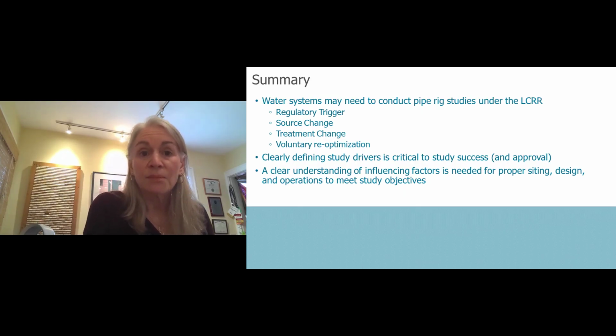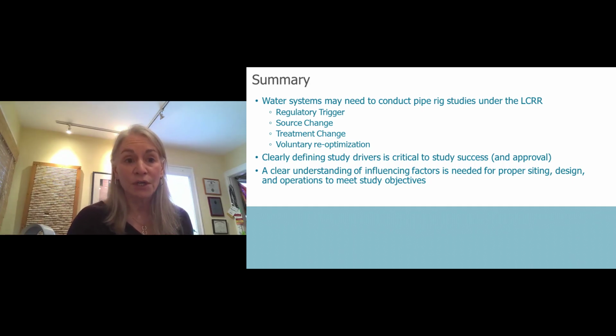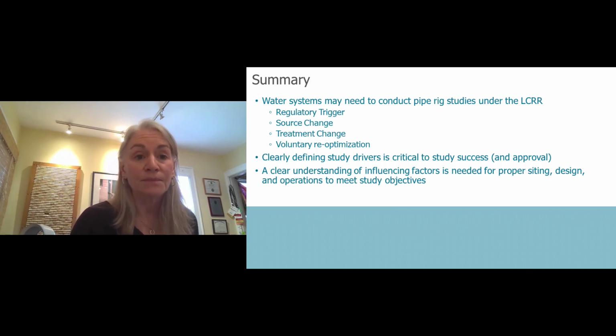So in summary, water systems may need to conduct pipe rig studies under the LCRR, and that could be due to a regulatory trigger, a source change, a treatment change, or you may voluntarily just want to re-optimize. It's been decades since folks have maybe looked at their corrosion control water quality parameters, and with the changing regulations, wanting to get ahead of the regs.